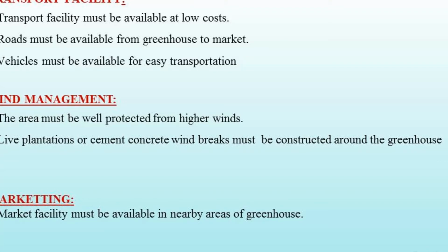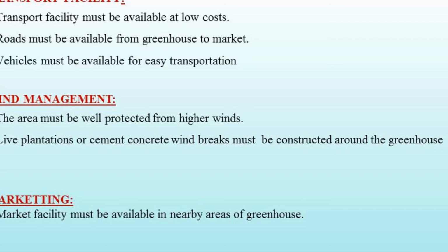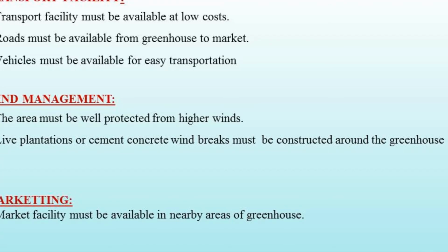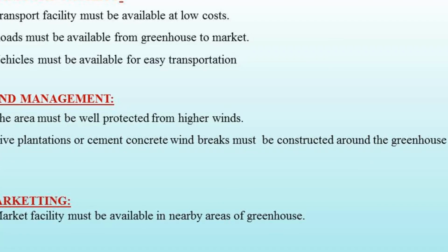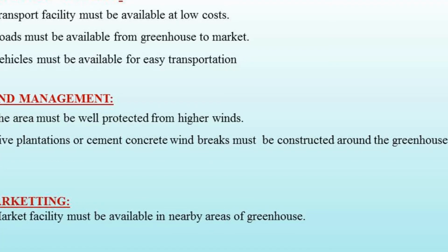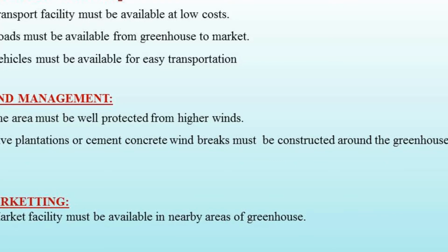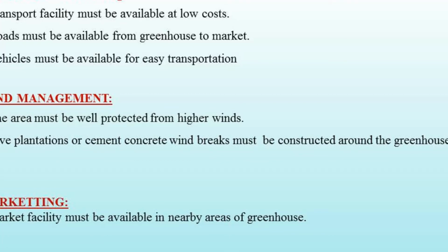That is, 15 mile per hour winds can double heat loss in a greenhouse. So well-designed windbreaks can reduce wind speeds by 50% and help to reduce heat losses by 5 to 10% as compared to an open area. And they can also reduce snow accumulation on the roof of the polyhouse.